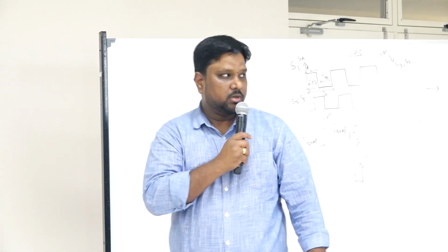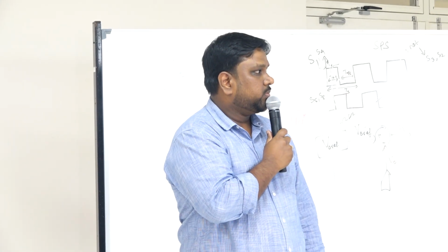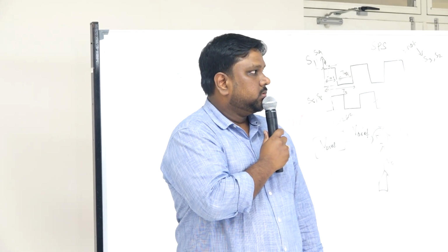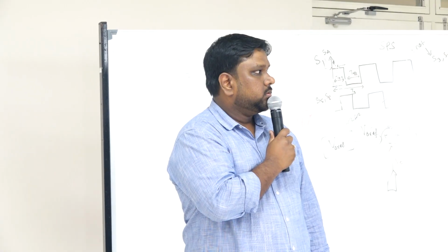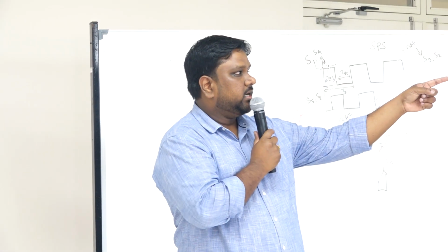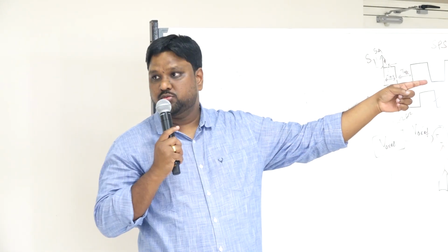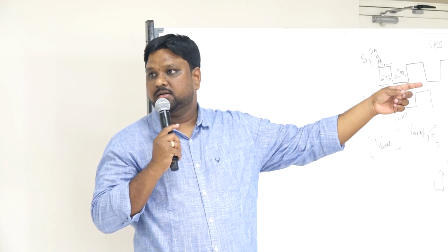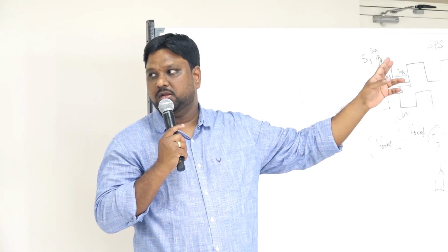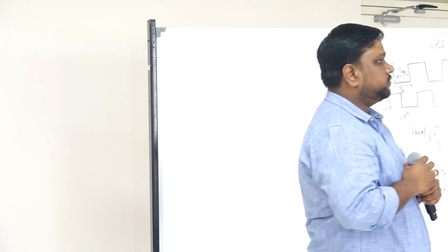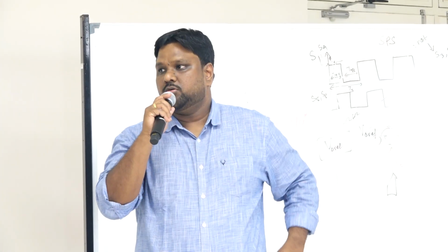Time delay. Double click that and open it to see what to set. You can just take it as it is. You have to select the delay type as transport delay. The delay type in the top one has 2 options. Carefully select the variable transport delay. Use it properly as it is done, and then put the Goto blocks and 0.